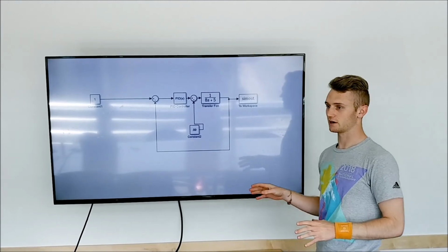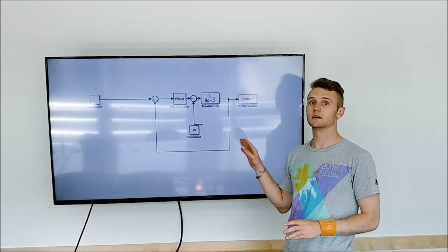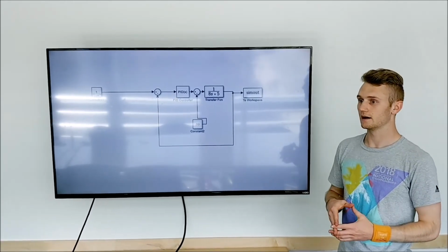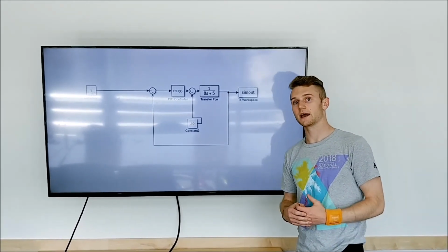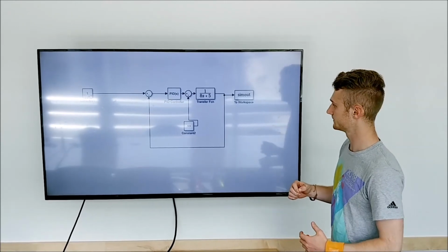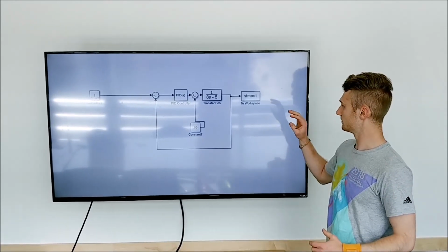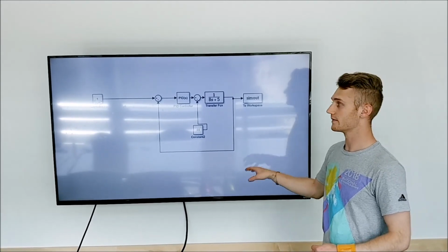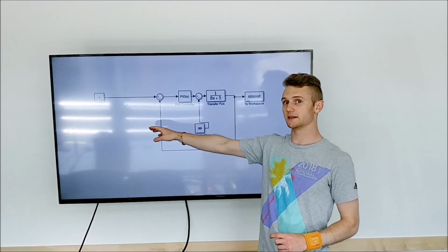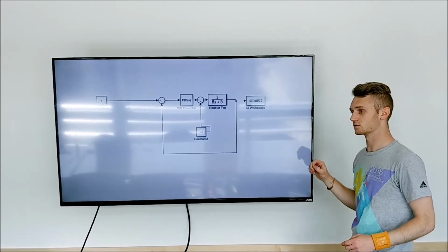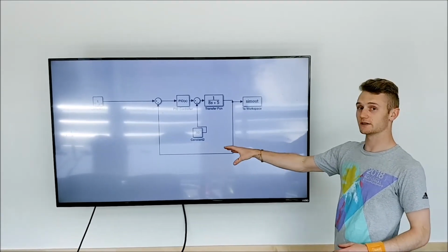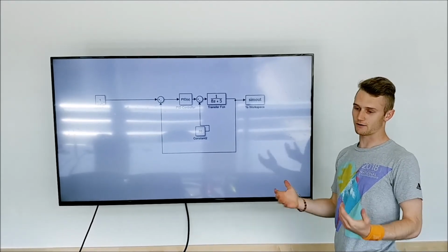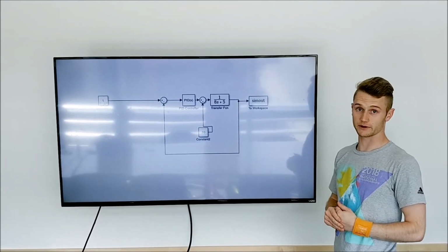We were able to do so with appropriate analyses and selection of a PID controller based on final value and steady state error analysis. We were able to make sure that the output frequency of the turbine always matched the input frequency from the grid, as well as reject disturbances from the load, the power of load from the grid.